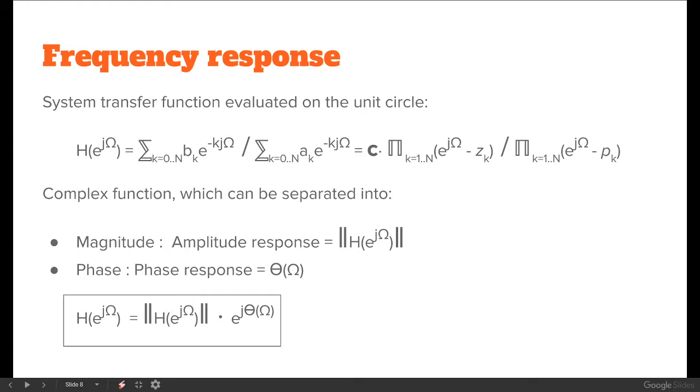So yes, now you can practically calculate the frequency response. You just need to vary the omega from 0 to pi. That gives you the frequency response. No need to evaluate the negative side, since, as you can see, it's always symmetric.